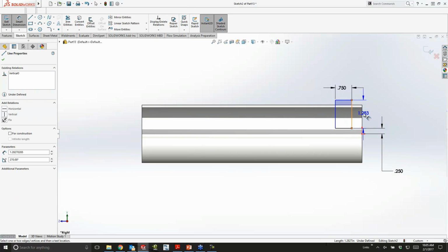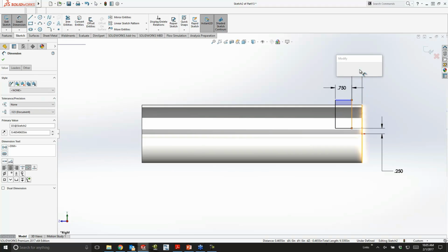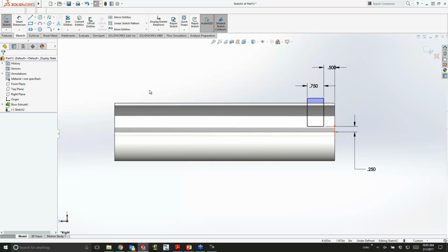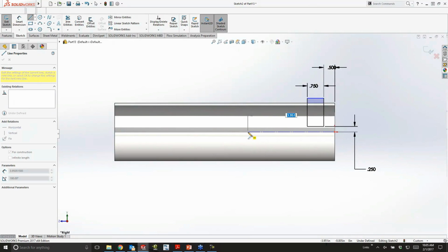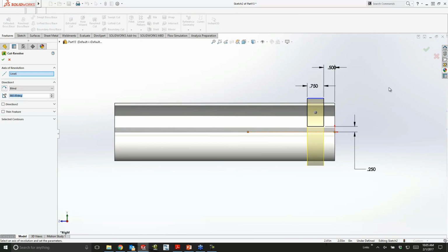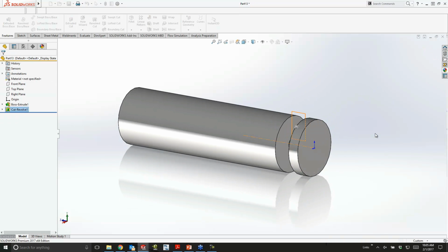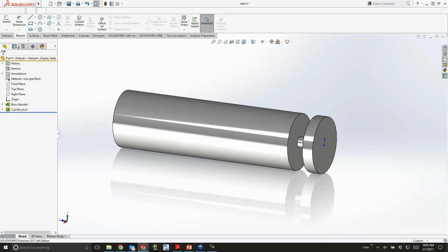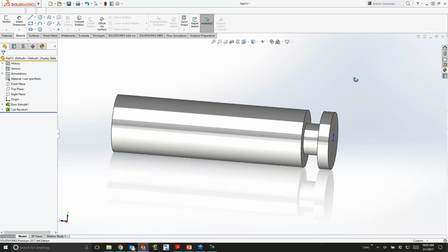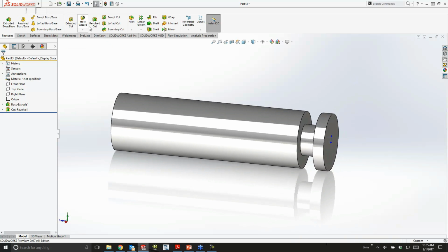And the idea here is that we're going to create various little baffles, and these baffles are going to create areas where the air can circulate, flow through and around. And real simple, just extrude, or I'm sorry, revolved cut here to create the first baffle area. And then we're going to do a pattern. It looks like the inside diameter is way too small. Let's make that a little bigger here. Then we're going to do a pattern of that baffle all the way to the end.